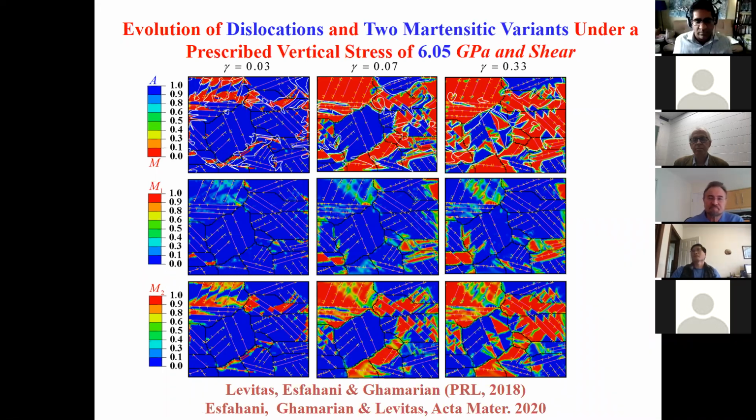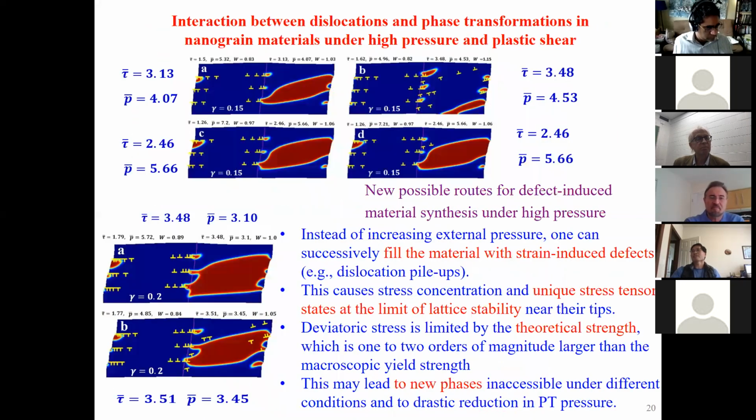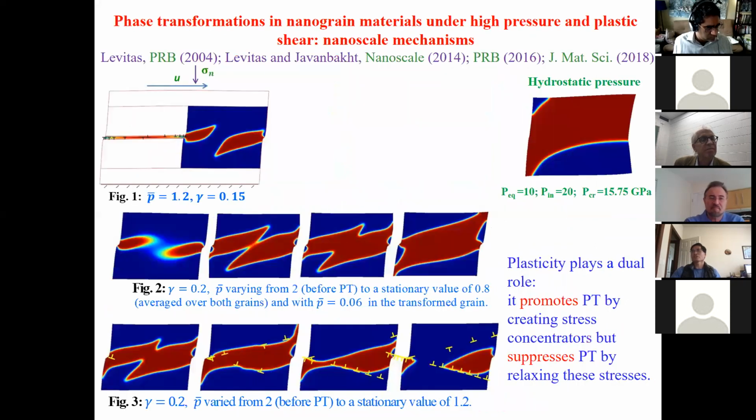Are you using the equilibrium profile of dislocation pile-up? Maybe the dislocation pile-up is not in equilibrium, right? So they have a different distribution, and if we have a different distribution of dislocations, you will get a very different dislocation stress concentration. So how may that affect this?